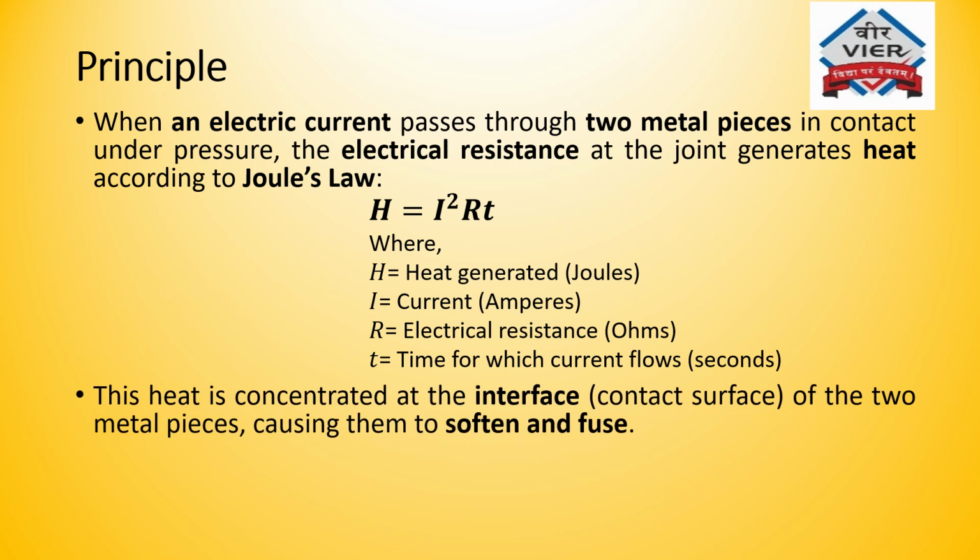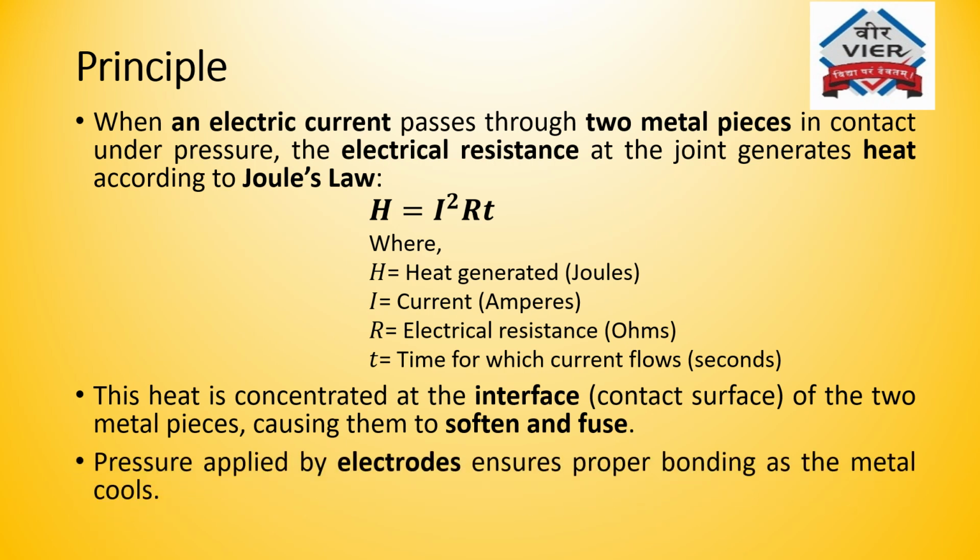The heat is concentrated at the interface, which is the contact surface of the two metal pieces, causing them to soften and fuse. The pressure applied by the electrodes ensures proper bonding as the metal cools.